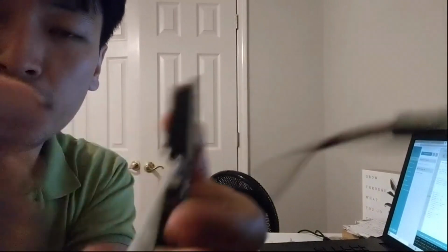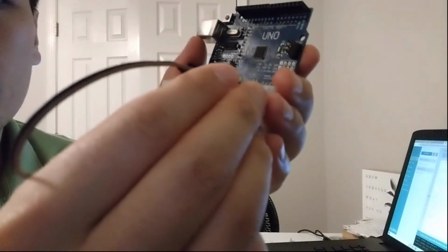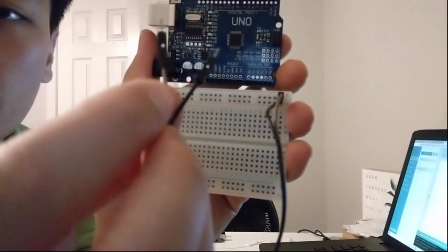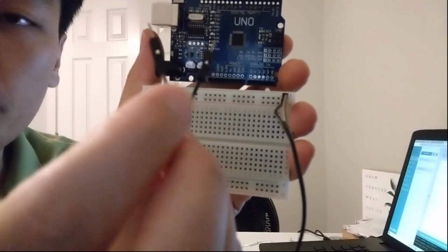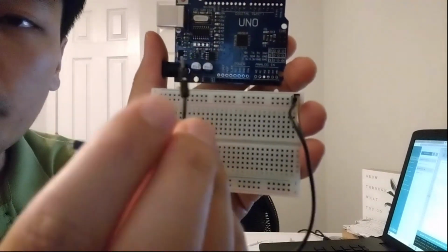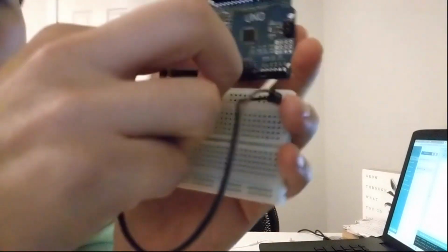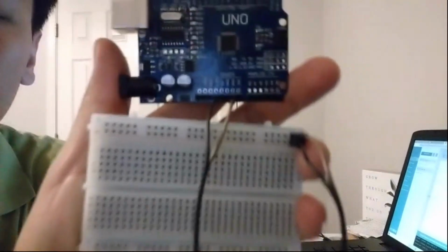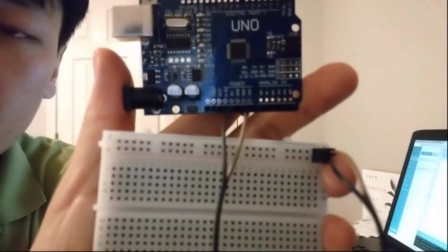What we're going to do first is connect the Arduino board and the breadboard just like the app. Make sure you have 2 wires, one at the top and the other one right below it. Brown is on the negative side, and the black wire is on the positive side, the red one. The black wire goes to the 5 volt power pin. For the brown one, which is connected to the negative, there are 2 ground pins.